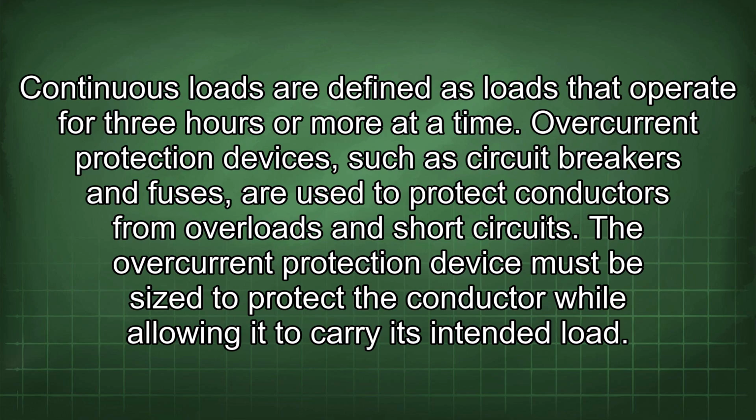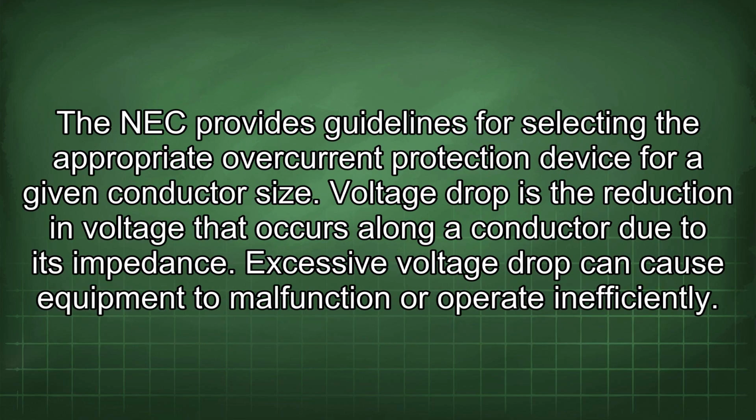Overcurrent protection devices, such as circuit breakers and fuses, are used to protect conductors from overloads and short circuits. The overcurrent protection device must be sized to protect the conductor while allowing it to carry its intended load. The NEC provides guidelines for selecting the appropriate overcurrent protection device for a given conductor size.